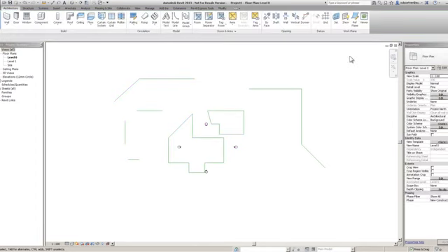This time I'm going to go from right to left, and again I'm just going to left click and hold and drag my mouse. You see this time it looks like a slightly different window, again similar to AutoCAD. Remember, after showing you all this stuff, AutoCAD is a swear word, but I will keep referring back to it just for now, to help you in this transitional phase. As you can see, the window is a dashed one, and as you've probably already guessed, the dashed one will highlight or soft select anything that it touches. It's more aggressive, it's quite nice.